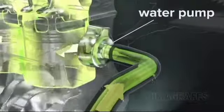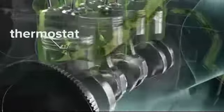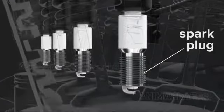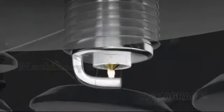A water pump keeps the coolant system flowing and properly pressurized. The thermostat regulates coolant temperature by either routing coolant back through the engine or to the radiator for further cooling. Electrical. The spark plug delivers the electrical spark that ignites the fuel-air mixture for combustion. The metal core is insulated from the outer metal casing with porcelain. The spark jumps between these conductive surfaces.